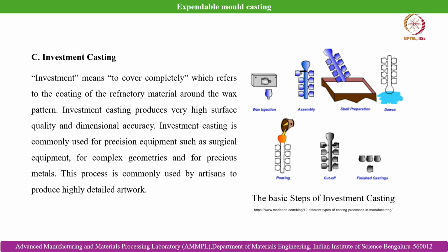Here comes investment casting. Investment casting is a typical example of the technique we can adopt when high accuracy and precision of the cast parts are in demand. Why can we achieve that? Basically through the ceramic shell preparation. We use the ceramic shell as the mold, where we fill the liquid melt, and thereby achieve the solidified, desired part geometry.